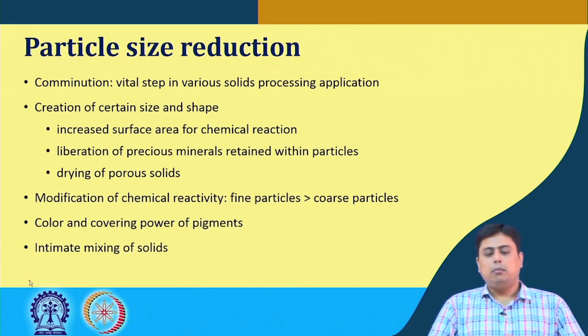Not only that, by creating this increased surface area through size reduction, in leaching, that means when we try to extract one component from the other, the depth of penetration of the liquid through these particles becomes less and less. So, it not only gives increased surface area, but also helps in enhanced leaching operation.